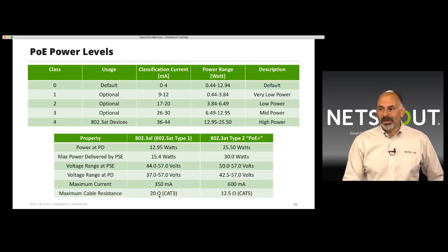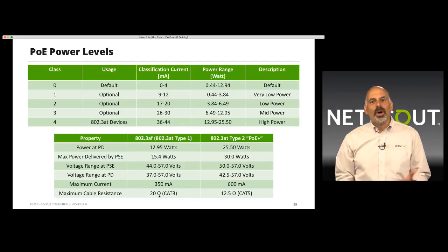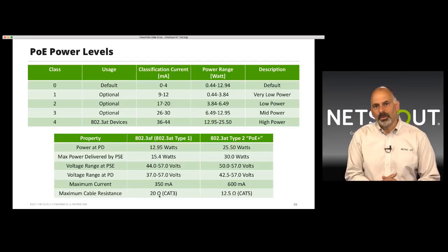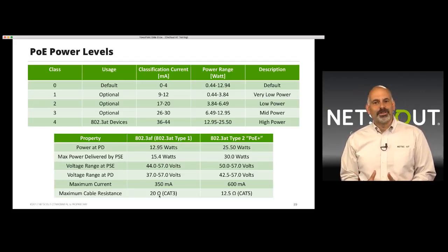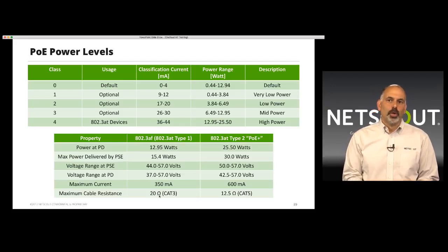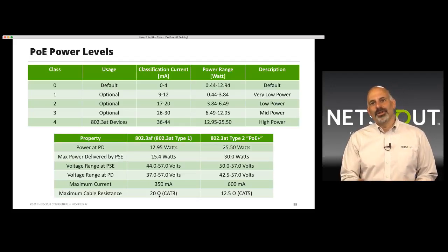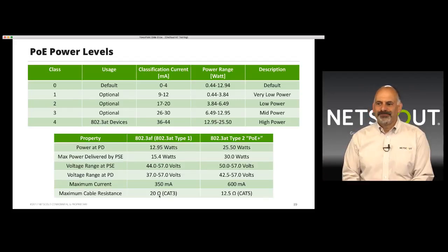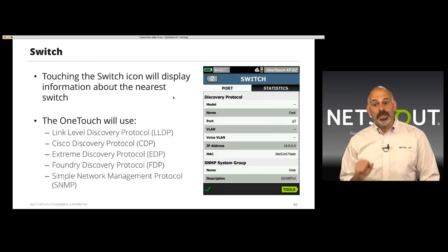Now, I was in Singapore a year or two later, and one of the folks doing a cable certification class handed me a roll of cable and said, "Can you tell me what's wrong with this?" I said, "Absolutely. That is aluminum." He said, "Wow, that's pretty good." Well, that's because I'd been exposed to it before. We do find that some manufacturers will break the rules by using aluminum wire, copper cladding it, and even putting blocks of concrete in the boxes of cable so that you think it weighs enough. So we've got to watch for that, and being able to validate PoE is a great way to do that.